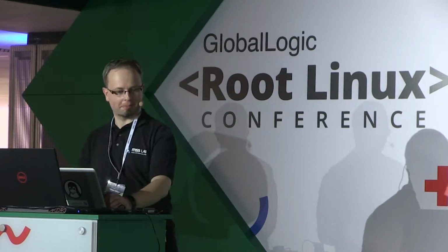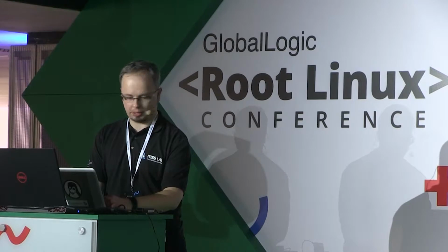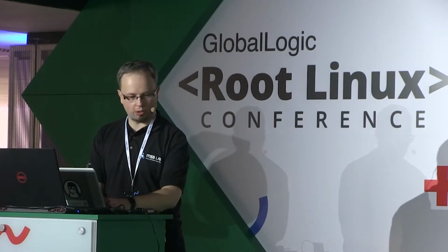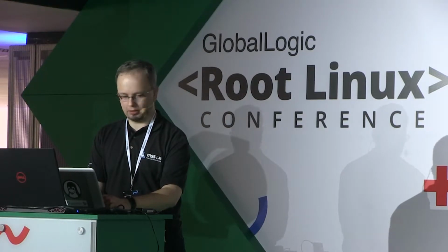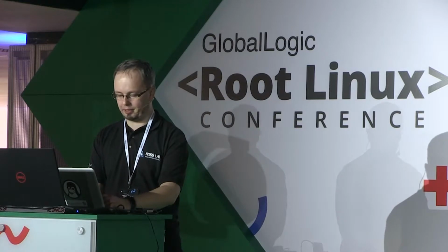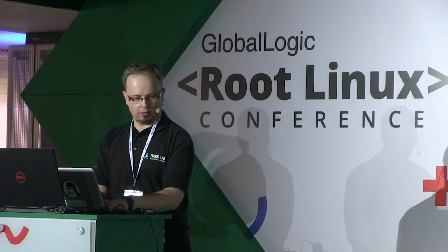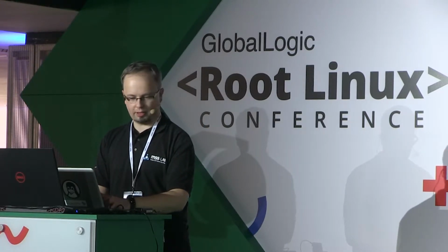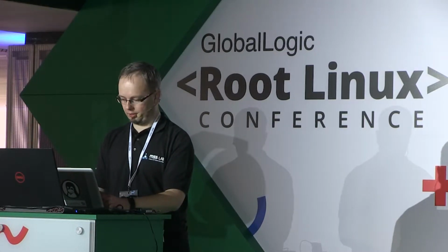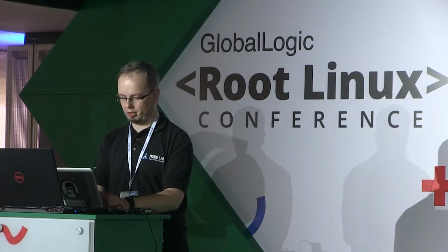The most helpful one. Okay, so we have a USB gadget directory. There, let's create our gadget. mkdir usb_gadget/g1. Let's enter its directory. Okay, we have some files and directories there. Now let's give our device some identity. I'm borrowing identity from an RNDIS gadget. It will be an RNDIS gadget that is a flavor of Ethernet, containing one configuration and one function.